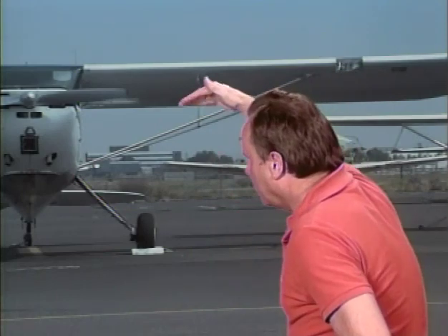All right, now let's assume you wash in the left wing of a monoplane for purposes of rigging corrections. Will that increase drag or decrease drag? Well, it'll increase lift and it'll increase drag. And so washing in increases lift, increases both drag and lift, and increases the angle of attack.